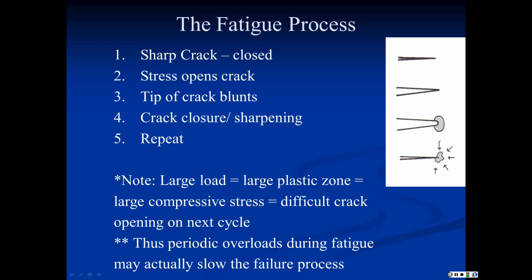What happens then is if the next load cycle is a smaller load, it first has to overcome all of this compression before the crack can begin to open again. And so you may, in fact, stop a crack from growing by overloading it occasionally. That is, if you hot dog in your airplane once in a while, you may arrest a lot of the cracks that are growing in the structure and then extend the life of the airframe. So it's a little counterintuitive. And we're going to look at an application of that in a little bit.